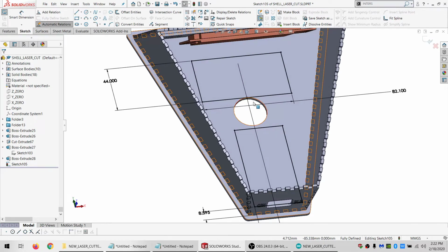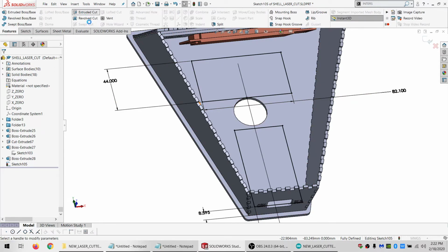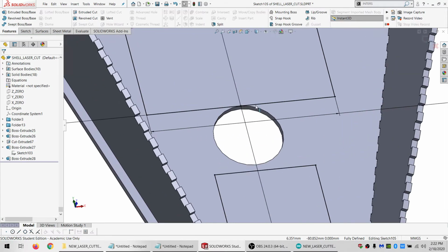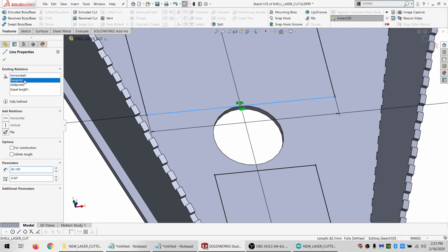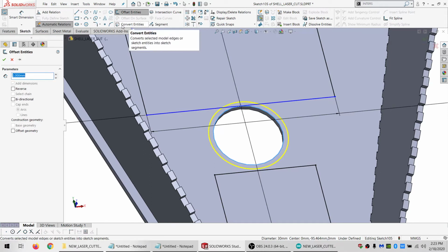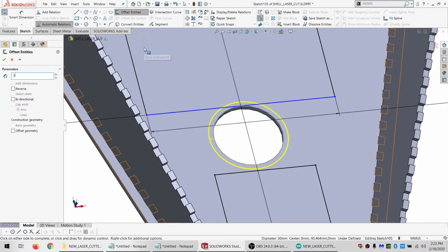And yeah, so we got our little outlines we can put down, and say 0.01. This tiny little thing. Oh, zero thickness geometry, of course. So let's get rid of this tangent. Let's offset this by just half a millimeter.